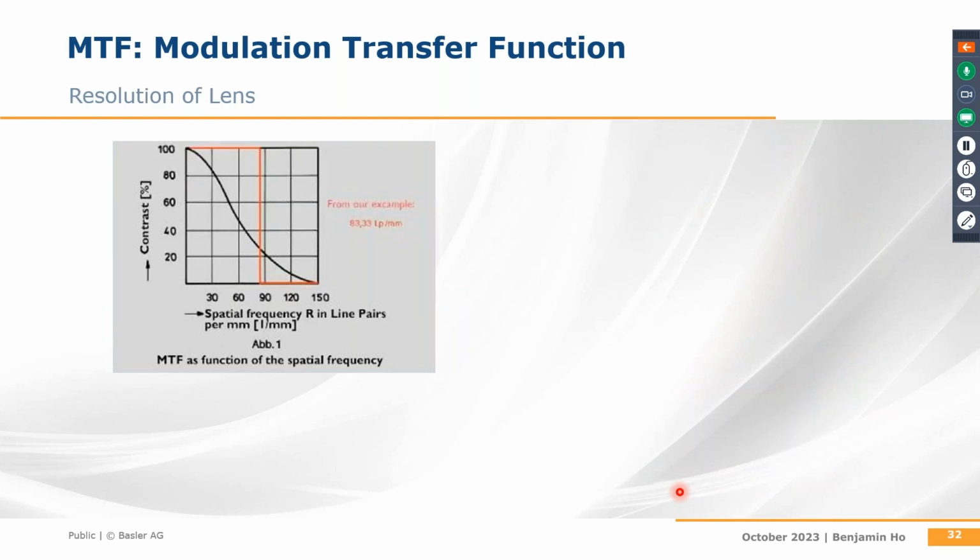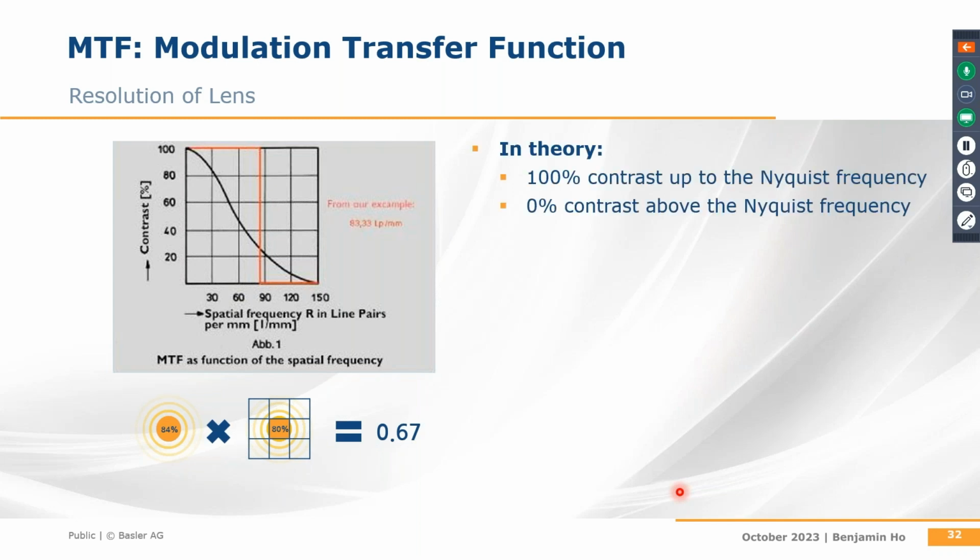In practice, lens manufacturers have decided to apply a more relaxed criteria when it comes to aligning lens performance with pixel size. This relaxed criteria involves multiplying the calculation result from the previous page by a factor of 0.67. In theory, not all the concentric circles of the Airy disk are affected by lens resolution. Only the first concentric circle has a significant impact.